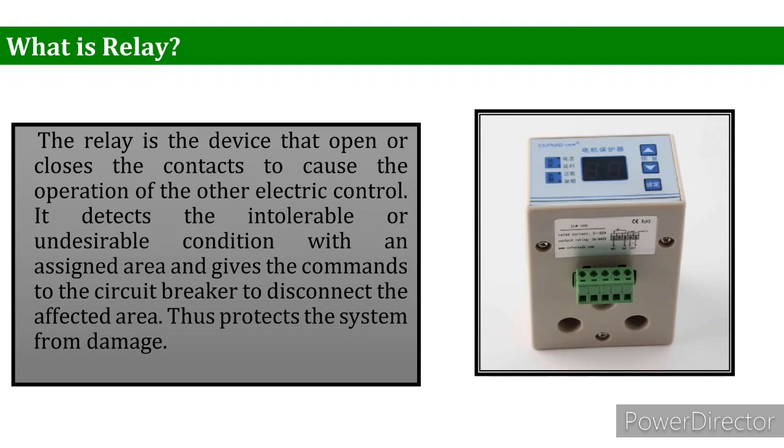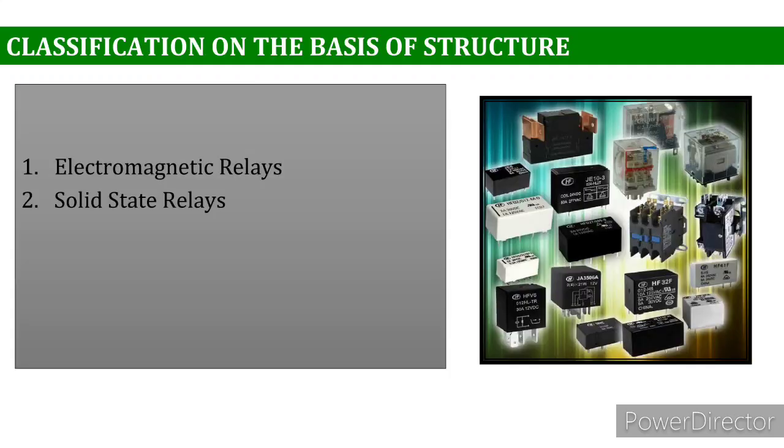A relay typically senses voltages or currents in its protection zone. It is programmed to give a trip command to the tripping coil of the circuit breaker if it senses a huge amount of current or abnormal voltage. By this trip command, the circuit breaker interrupts the circuit and isolates the faulty section so that the rest of the power network remains stable.